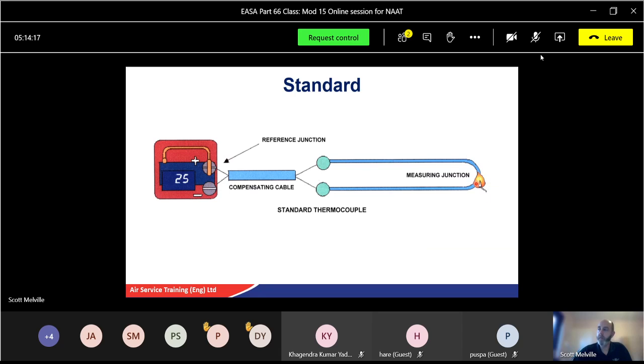So the hot zone here, again, we'll use these in exhaust as well. We have exhaust thermocouples, which use the same principle, not for fire detection, but certainly for the exhaust gas temperature. So another form of thermocouple. But certainly we can have thermocouples in a fire system. It does the same thing. Once it gets to a certain temperature, the voltage will go up, and at a certain voltage, it will be multiplied through an amplifier and give a warning in the system.